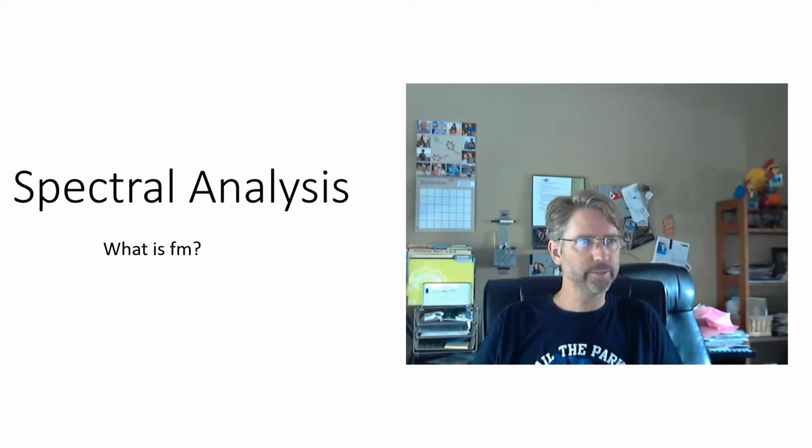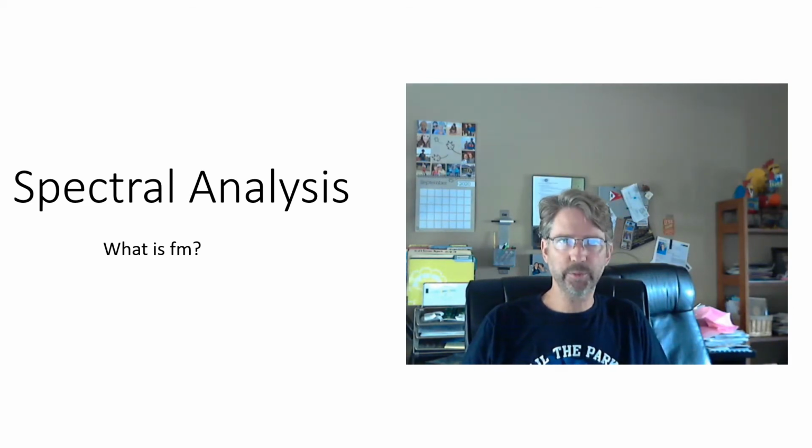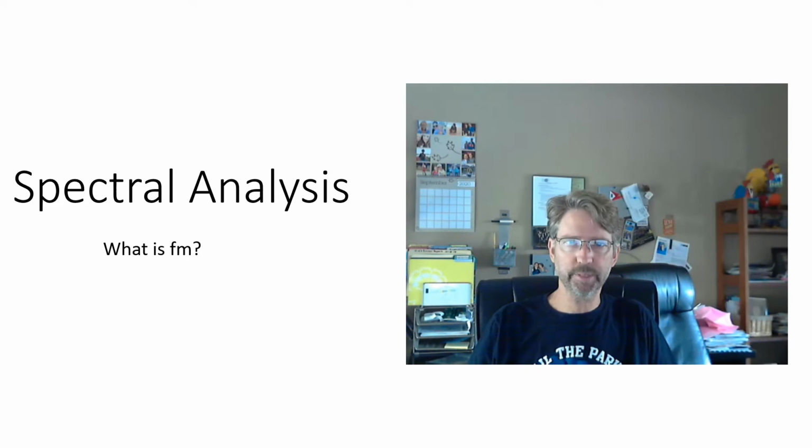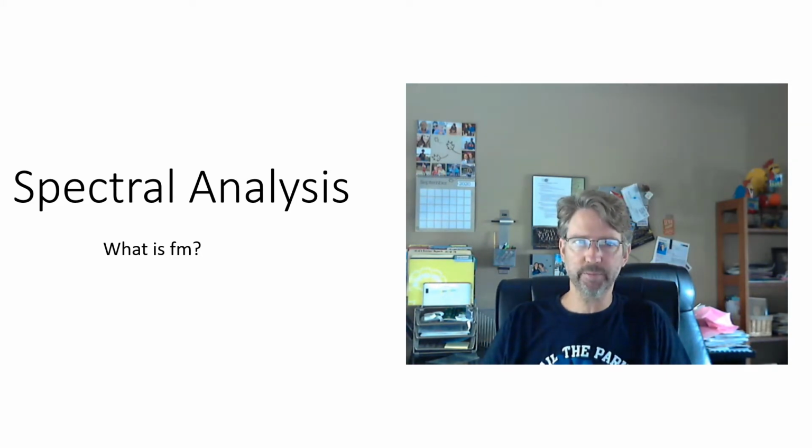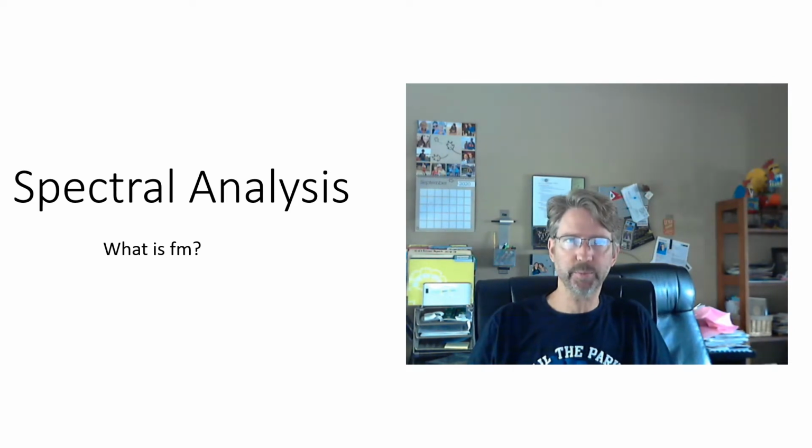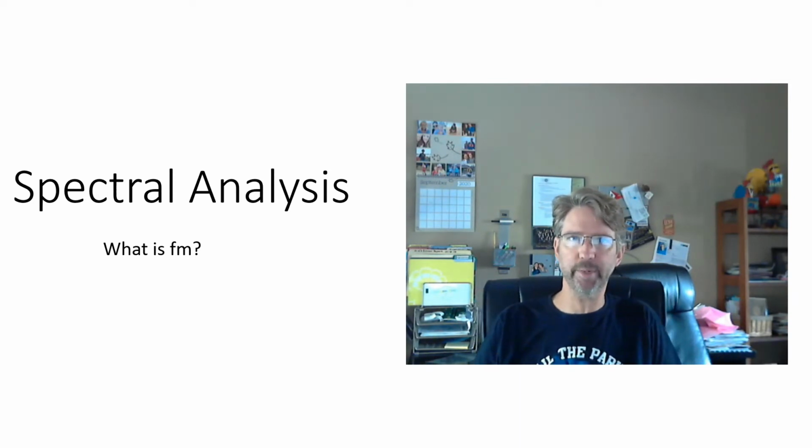Well, hello there. So in this video, we will introduce the concept of using spectral analysis for the sampling theorem. There are lots of reasons to do spectral analysis, which finds frequency content in signals. But in this application, we're going to be using it to find out what's the maximum frequency in a signal so that we can sample at least twice as fast as that by the sampling theorem.